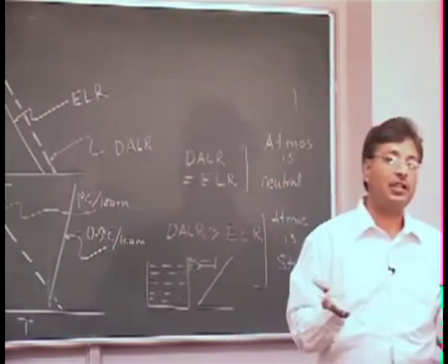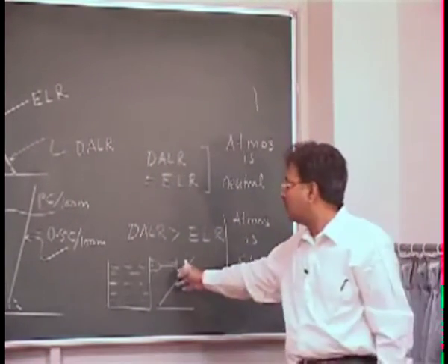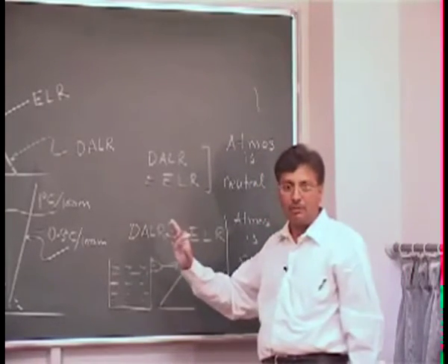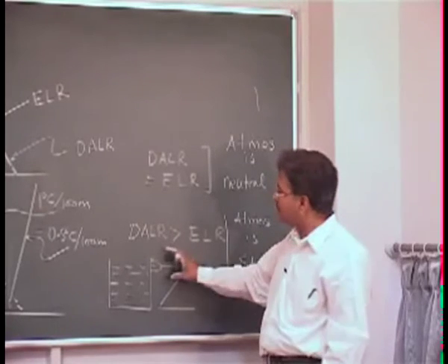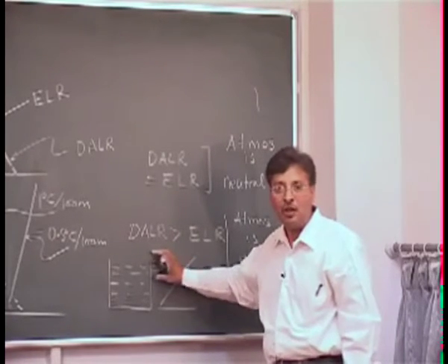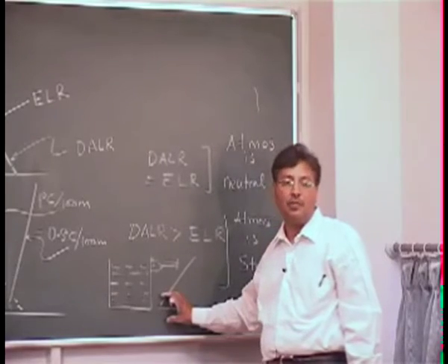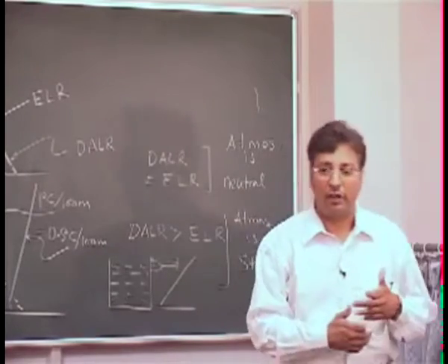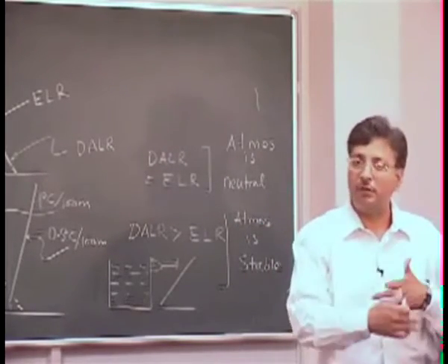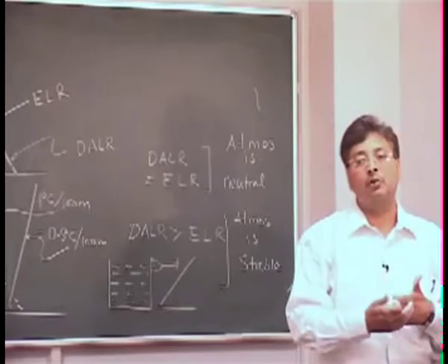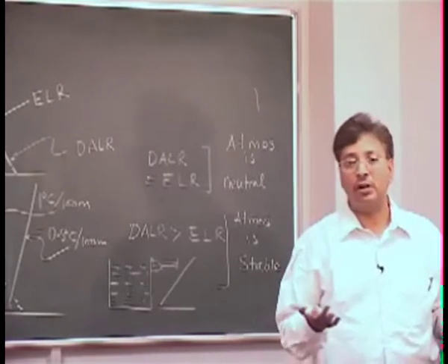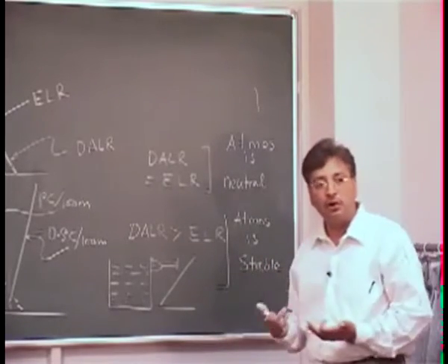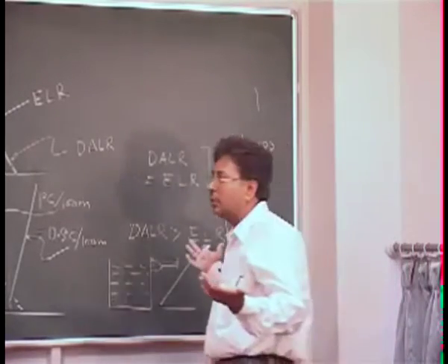And the same thing in the atmosphere. I gave you the example, but if you look at the atmosphere, in some sense, how it is done is a different thing, it is being heated up from the top and the temperature is lower at the bottom. So as a result there will be no convections, no currents, no turbulence, no mixing, and we will call that stable. Water is sitting stable, so the atmosphere is also sitting stable, which means pollutants will not travel or jump or do the things they normally do.